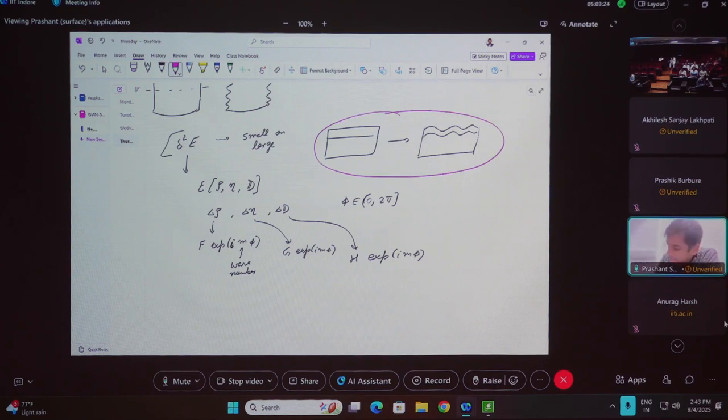And when you put them back into whatever equations you got from the second variation, you eventually get the same problem. You get a matrix, you get a vector, you get a zero. And you say, okay, a non-zero solution can exist only when the determinant of M equals 0. So the process is pretty much the same. In a lot of these instability problems, whether small or large, you end up following a very similar recipe.